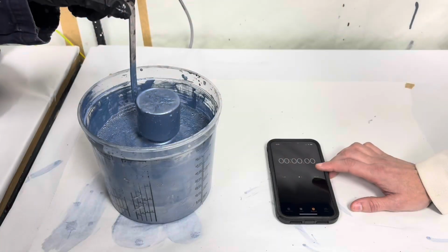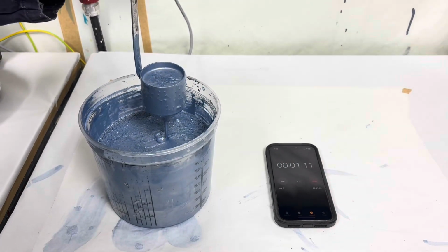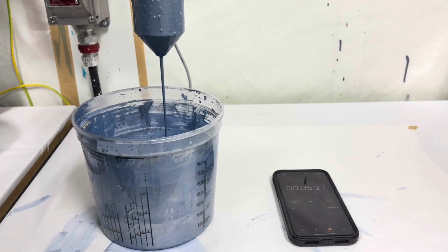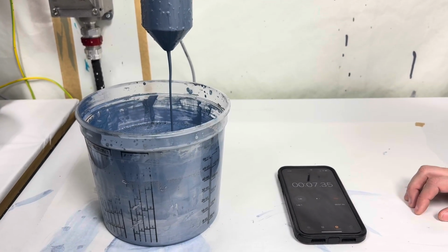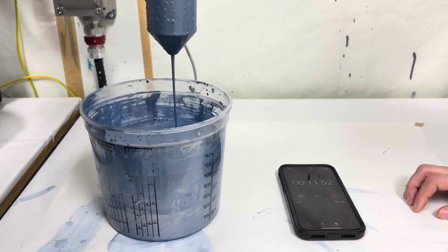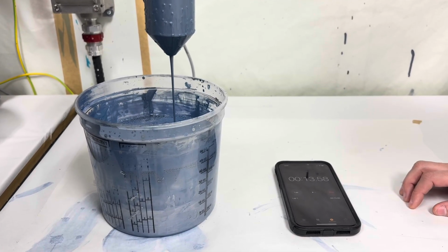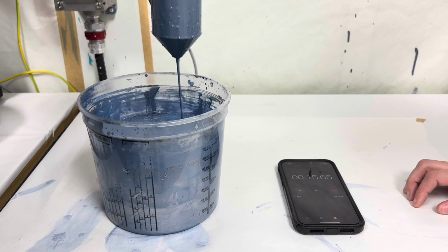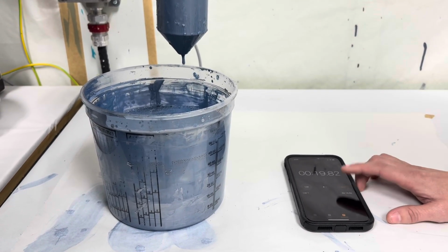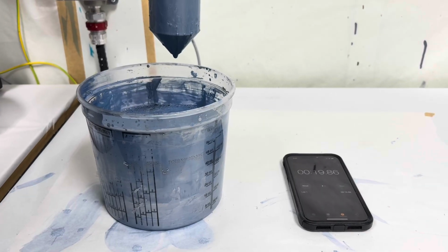Before we continue with our application, we always want to make sure that the paint is mixed appropriately. One of the measurements that we do is called viscosity. Viscosity is a material's resistance to flow, and we use a viscosity cup as seen here, dipped into liquid and then timed. The amount of time it takes to have the liquid come out and then start to sputter, as we see in this moment, is the viscosity.